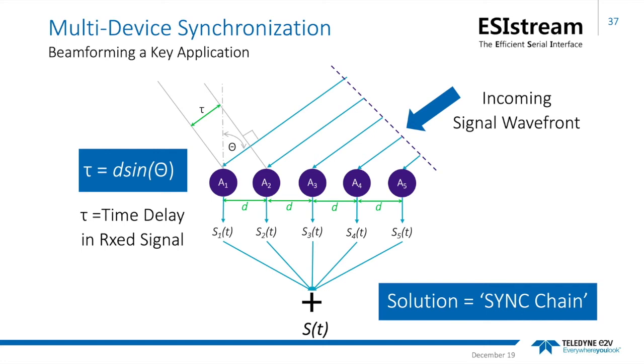Any time delays, especially variable ones across the electronics that samples the received waveform, will create phase error in the system. The physics of this system, highlighted in the diagram, is that applied in many beamforming radio and RF systems in widespread use today.